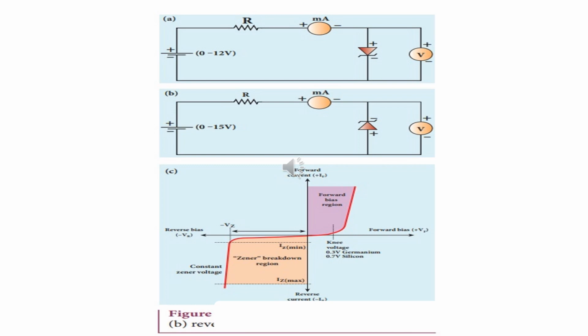The avalanche breakdown is observed in the Zener diode having Vz higher than 6 volt. In the reverse bias condition, the conduction will take place only due to minority carriers. As the reverse voltage applied to Zener diode is increased, these minority carriers tend to accelerate. Now, these newly generated free electrons will accelerate. They will knock out some more valence electrons by means of collision. This phenomenon is called avalanche multiplication, and in a short time a large number of free minority electrons and holes will be available for conduction, and the carrier multiplication process becomes self-sustained. The self-sustained multiplication is called avalanche effect.